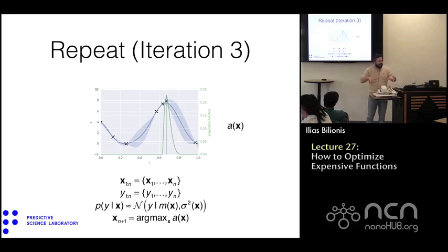So when you start these algorithms, the best thing to do would be to start from a Latin hypercube design. So you say you have a budget of 100 simulations or 100 experiments. Well, the first 5, pick them randomly. Then start this thing, okay? Because it is actually possible to get garbage if you start from very few simulations and you're very confident about the hyperparameters of your Gaussian process and all that.